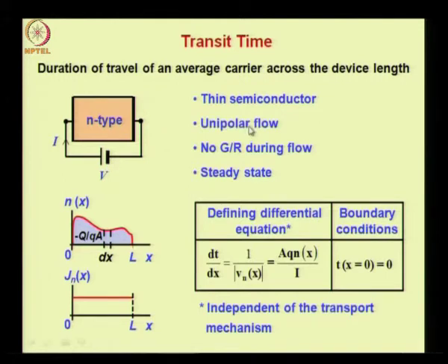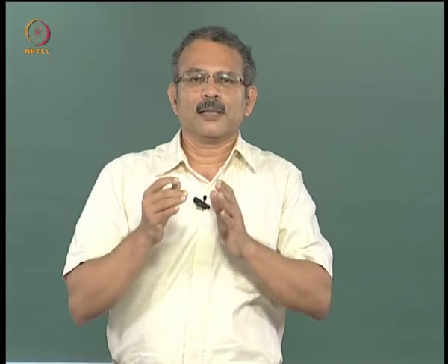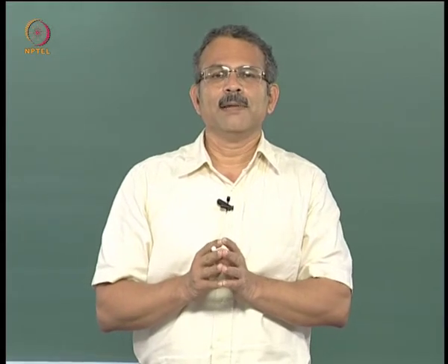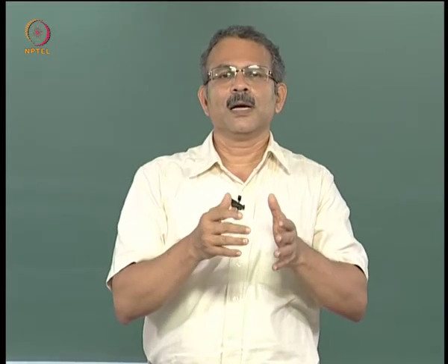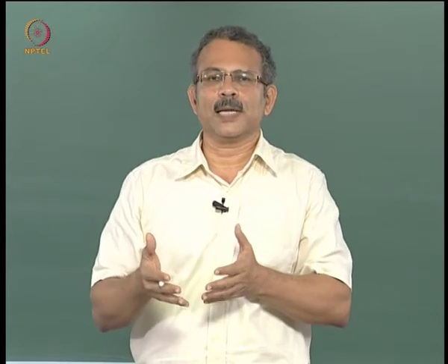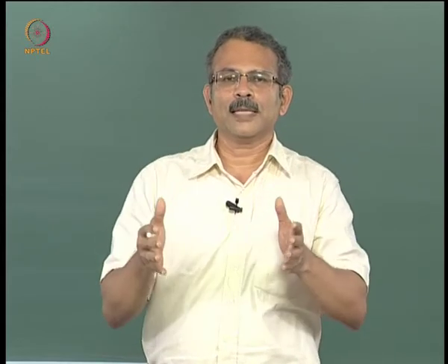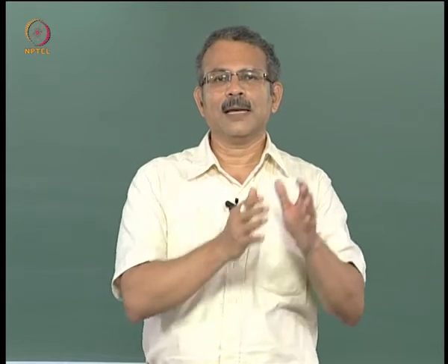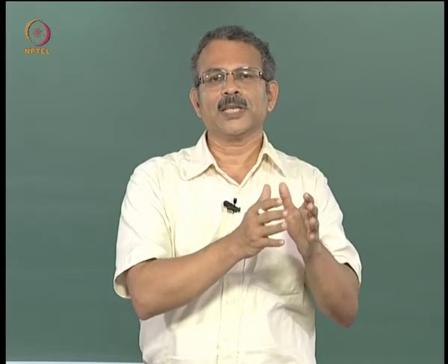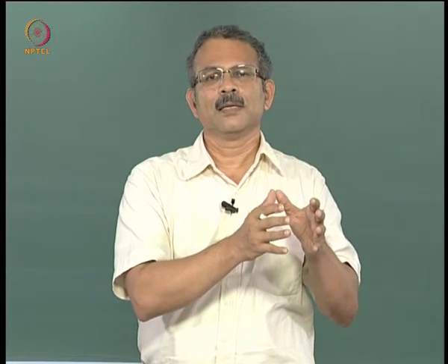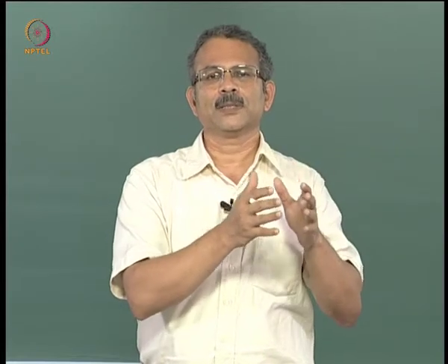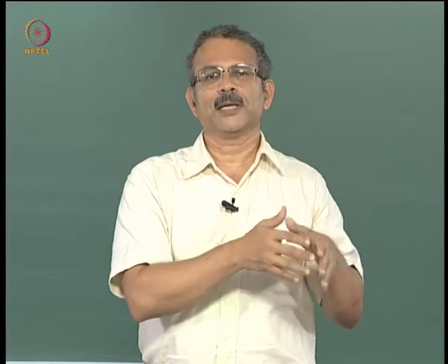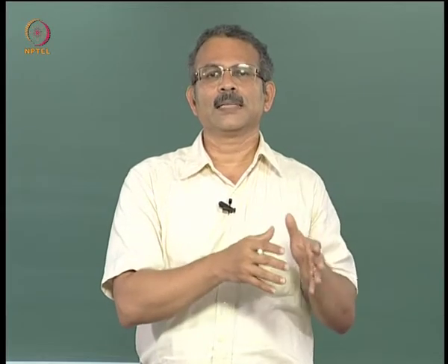We talked about the transit time, which is the duration of travel of an average carrier across the device length. Now the transit time was not associated with the return of some disturbed situation to equilibrium or charge neutrality. So the transit time discussion was a little different from the discussion and the equations associated with momentum and energy relaxation times, directed relaxation time, minority carrier lifetime, diffusion length and Debye length.